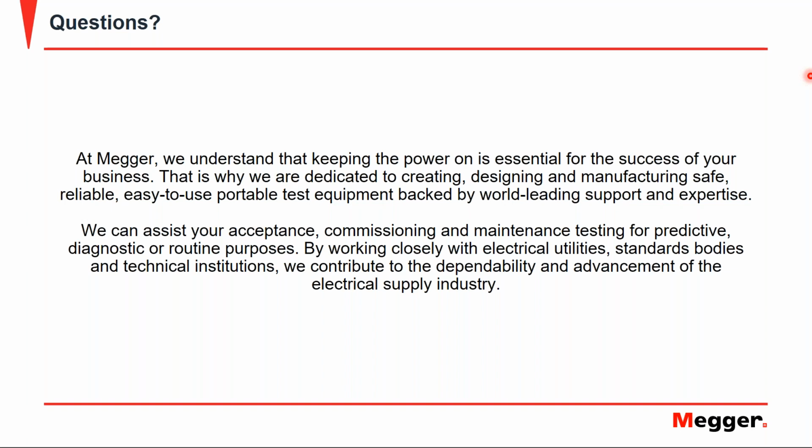As those cable drums are PD tested and then going into the field, those levels of discharges we will not see in the field. So if there is a damage of the outer jacket, as already mentioned before, then the PD level will be in the range of 100, 200, or 300 picocoulomb. If there are problems in the accessories, then the discharges can be up to several nanocoulomb height. So the 5 picocoulomb accuracy in the field is in most cases not possible, but also not needed. And the reasons have been explained already.